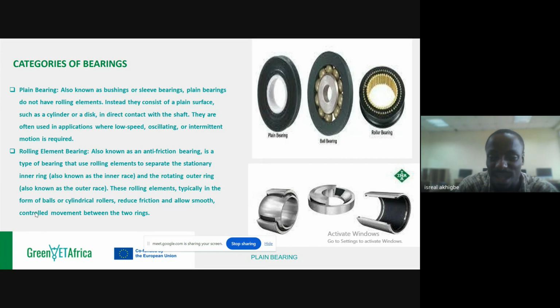That equivalent was already given a specified rating by the manufacturer. So you don't want to buy another type of chain for a sprocket just because it looks like it's matching. You have to ensure that it's the same dimensioning. Get the dimension right. For the dimension to be what it is on that machinery, it has been specified by the manufacturer that this will handle a certain weight, which is usually known to the manufacturers alone. So you just take that chain to where you want to replace it, they get those values out and they give you an equivalent. Okay.